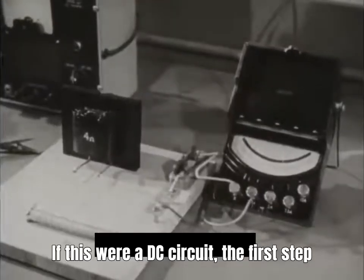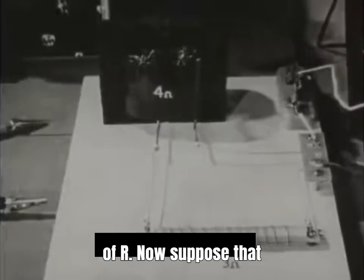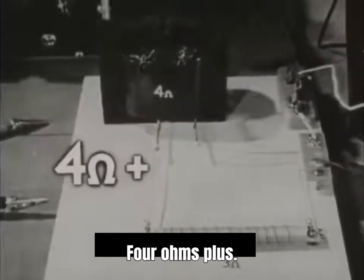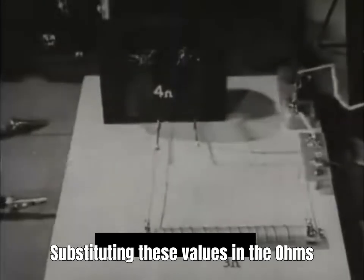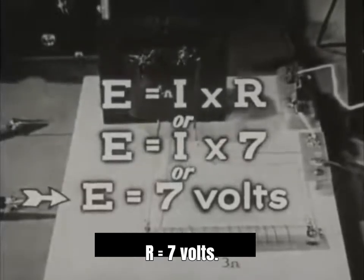If this were a DC circuit, the first step in calculating the voltage at the source would be to add together all of the series resistances to get a total value of R. Now, suppose that in this RL circuit, you add arithmetically the resistance and reactance. 4 ohms plus 3 ohms is 7 ohms. Substituting these values in the Ohm's law formula, you have E equals I times R, or E equals I times 7, or E equals 7 volts.